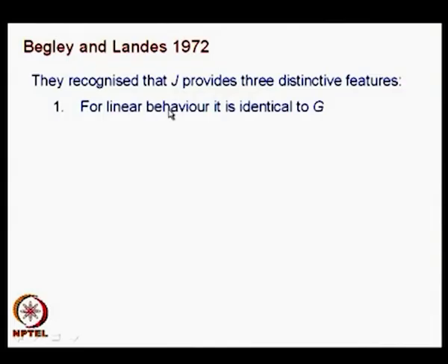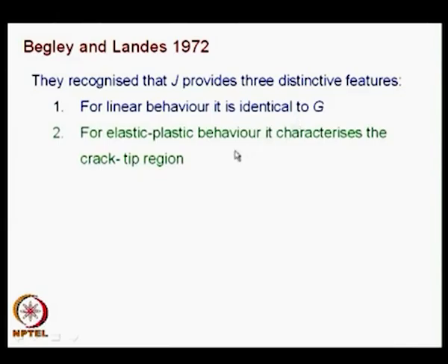For linear behavior, J is identical to G. So, that gives a comfort that we are going in for generalizations. For elastic plastic behavior, it characterizes the crack tip region, like K determines the strength of the stress field in linear elastic fracture mechanics. In elastoplastic fracture mechanics, the strength of the field is determined by J.